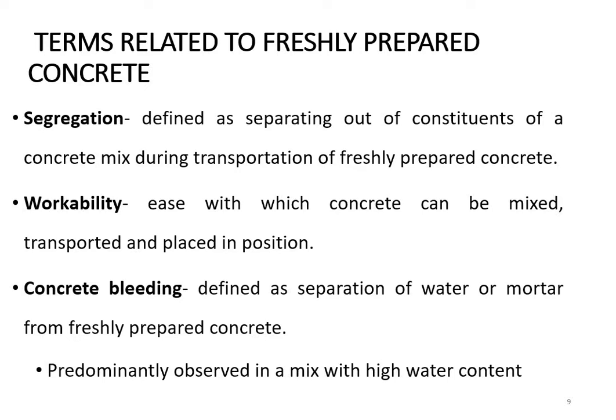The next term is concrete bleeding. Bleeding of the concrete means the separation of water or mortar from the freshly prepared concrete. That is, the water or mortar gets separated out and comes to the top. That is known as bleeding. These three terms or phenomena must be taken into consideration while you prepare the concrete.